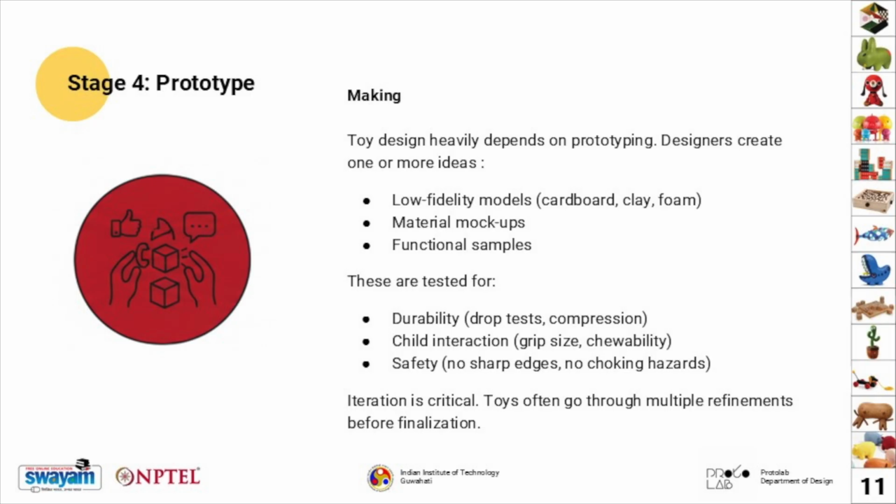These prototypes are tested carefully to ensure they meet functional and safety standards such as durability, which is drop test and compression, and child interaction such as grip size and chewability test. Safety test is for no sharp edges and no choking hazards. Also, at this stage, iteration of model making is critical. Toys often go through multiple refinements before finalization of design.